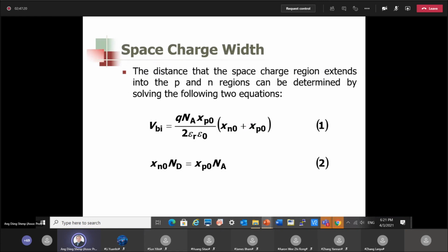So there is no interdiffusion of majority carriers, right? In an intrinsic semiconductor, the electron and hole concentrations are constant throughout. So there's no more junction, no more space charge region, no more built-in field and no more built-in potential, of course.